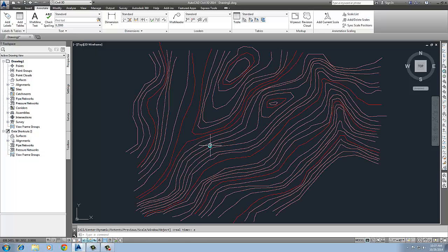Follow that up with a zoom extents just to make sure that it's there. Click on it. You should see it's a block reference. Okay, so what we're going to do is explode that block. Okay, and now you have individual polylines. So this is not the best method as we've talked about in the past, but this works very effectively and it's a good process to know.